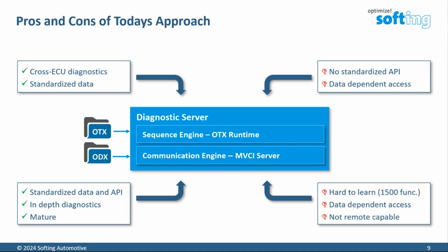For MVCI, well, the cons are, it is very hard to learn. We have 1,500 functions. We see many OEMs struggling with it to get efficient programming done. You again have data-dependent access. This means inside your code, you need to know what the service name is, what the parameter name is. You need to be an ODX expert, an MCD expert, to be able to even write a simple application. And also, it is not remote capable.